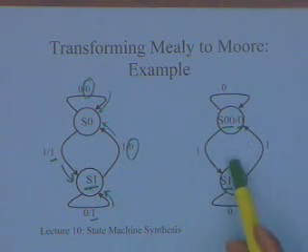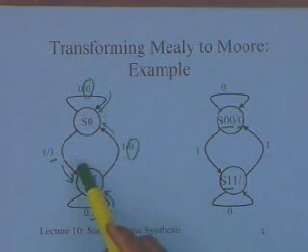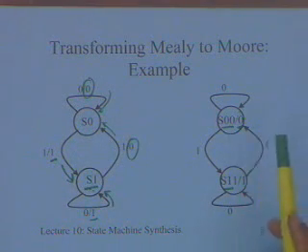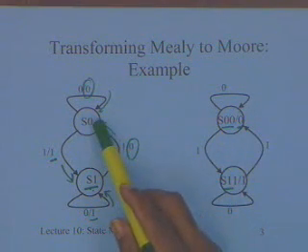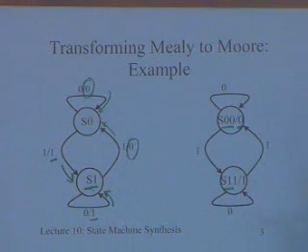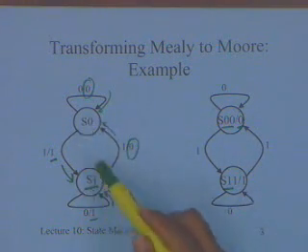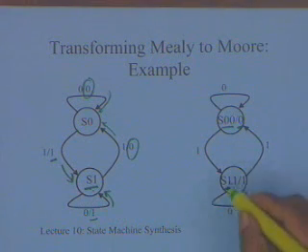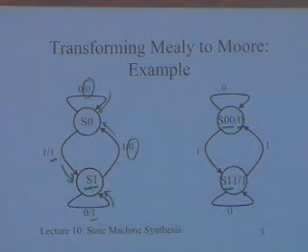So, when the number of states increases, they cannot decrease. Okay. If this is a minimized Mealy machine, I cannot have a fewer number of states in the Moore machine, I can only have a larger number of states, because each state which has incident edges with multiple outputs gets split into multiple states. In this case, it so happens that both the states have all the incident edges with the same output, and because they have the same output, I do not split. We should typically rename them, because they are actually different states.